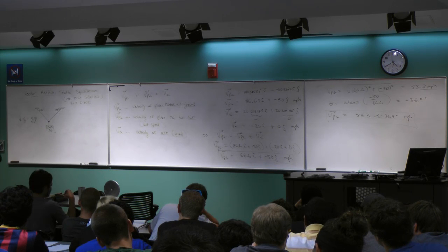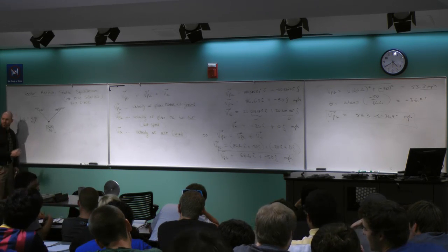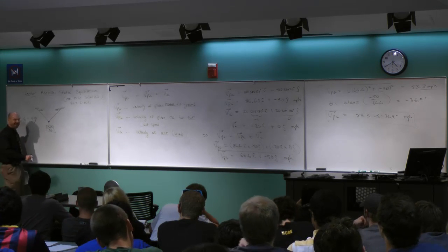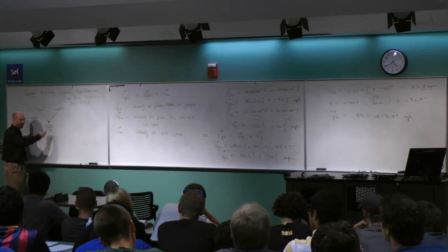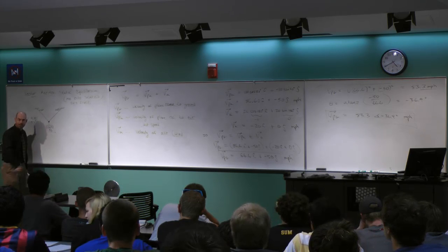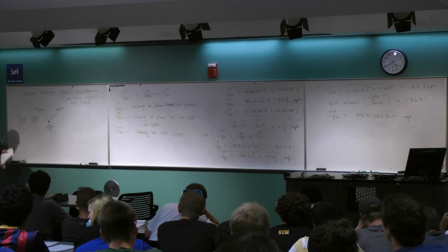So as long as you're aware, just look at these statics problems, and when there are problems that have weights and stuff, if it's SI, you probably got to multiply by g. Okay? If it's English, typically it'll be labeled in pounds, and you already got a weight. Okay? So make sure you're operating accordingly.